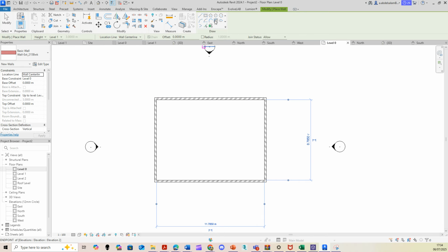If I go to fillet arc here, select this one, this is gonna fillet the curve. Do you get what I mean? And then you could also put a certain radius for that. So let's say it's 1, and then if I just select this one, automatically it's 1. Select this one, automatically it's 1.